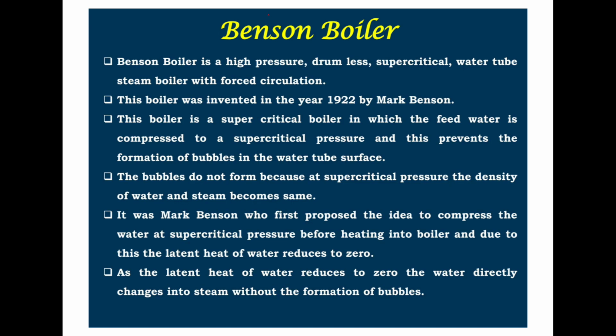The Benson boiler is a high pressure drumless supercritical water tube steam boiler with forced circulation. This boiler was invented in the year 1922 by Mark Benson. It is a supercritical boiler in which the feed water is compressed to a supercritical pressure, and this prevents the formation of bubbles on the water tube surface. The bubbles don't form because at supercritical pressure the density of water and steam becomes the same.